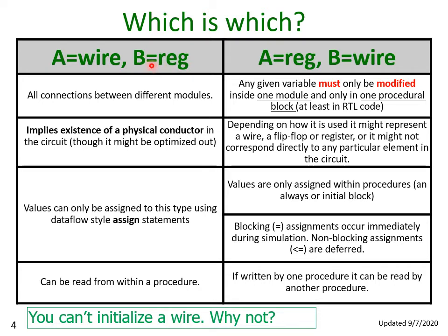language, or a sequential programming language, would function. The wire type is a bit more intuitive in that it fairly directly corresponds to the presence of a wire in the resulting circuit. That's not to say that the synthesis software might not optimize it away if it figures out that it isn't needed when it combines some other logic somewhere.